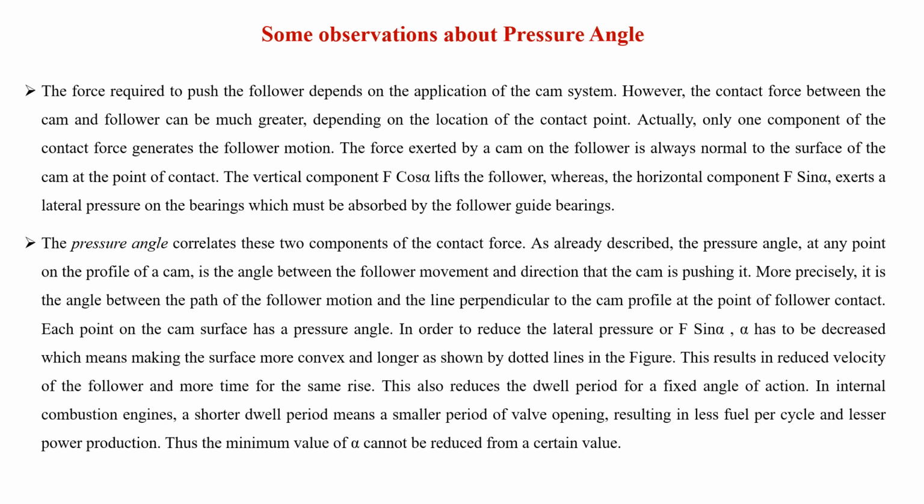There are certain observations which should be clearly understood about the pressure angle. The force required to push the follower depends on the application of the cam system. However, the contact force between the cam and follower can be much greater depending on the location of the contact point. Actually, only one component of the contact force generates the follower motion.